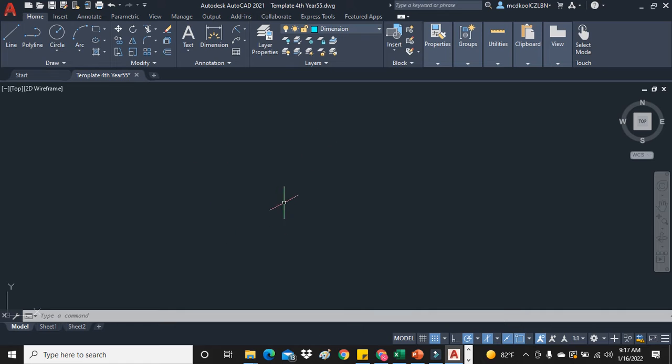If I wanted to draw a line, I can go up here by my line tool, or I can type in line. So when I typed in line, you realize that my cursor changed. If ever you want to deselect a tool, or if you're unsure about a tool, you press Escape on your keyboard. When no tool is selected, you will see the white square on the cursor. So I'm just going to go up here, left click line, and you realize that the white square on the cursor is gone. I press Escape to deselect. I go up here, select it again.